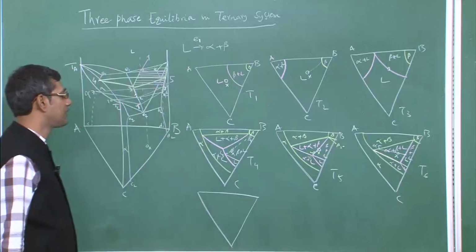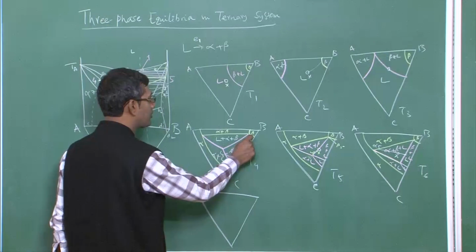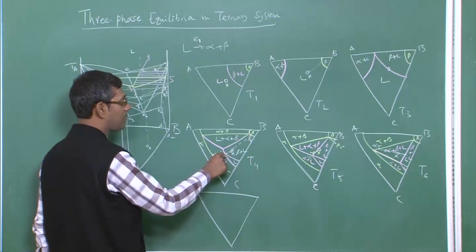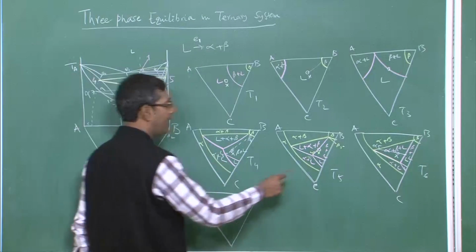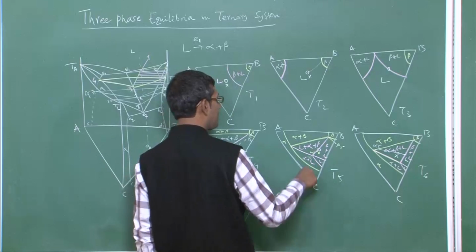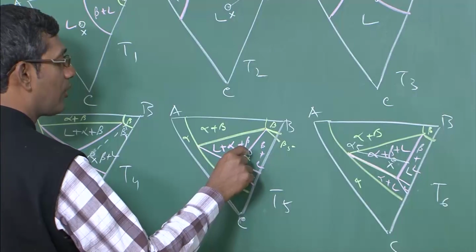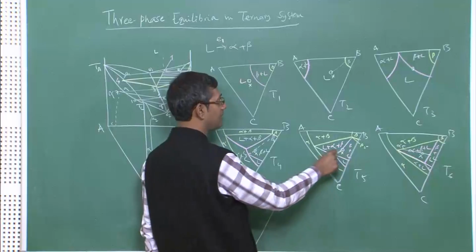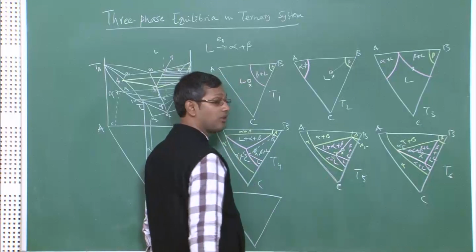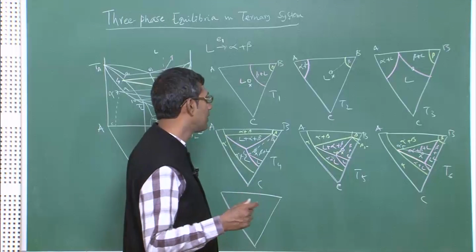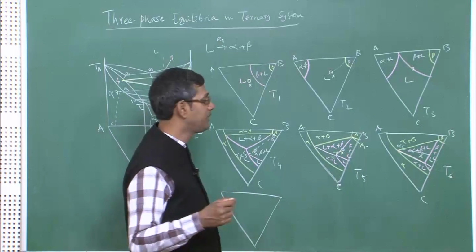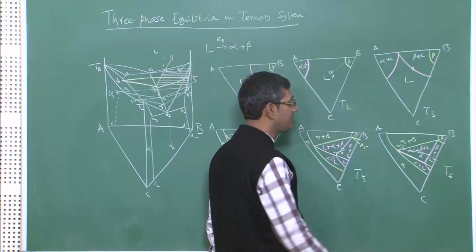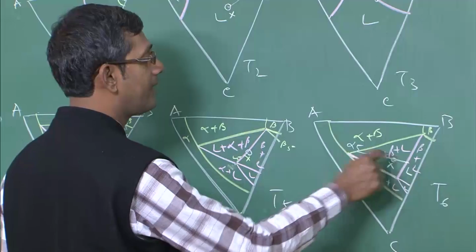The thing which is clear to you is that at temperature T4 it was precipitating only beta, and the beta composition was beta 4, okay. And this composition of beta was in equilibrium with the liquid composition of L4. At T5 the temperature has dropped so much that the alloy composition is sitting on x, and x is basically sitting on this boundary between the 2 phase field and the 3 phase field, correct. So, therefore, it is still precipitating beta, it is not yet precipitating alpha, basically thermodynamically it can start forming alpha. Now, at T6 this alloy composition point moves inside the 3 phase triangular region, you can see here, there it can precipitate alpha.